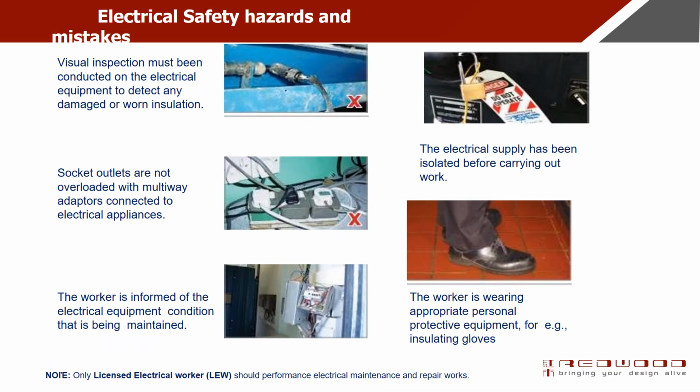Electrical safety, dos and don'ts. Do not plug multiple sockets into a single outlet to avoid overloading. Do not touch or open the main DB box, only authorized and licensed personnel are allowed. Do not use damaged cables or electrical equipment.